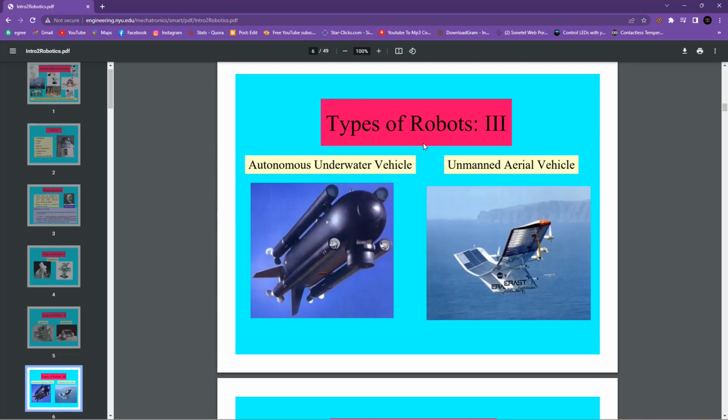In case the drone is in the air and it encounters wind, it's going to change direction or lose control. So the drone has been programmed to balance itself with some sensors. For example, the gyro sensor is able to measure the angle of tilt of the drone. If it reads any angle that is not supposed to be read, it can sense that and send a message to the microcontroller to balance the robot with the help of the actuators, which are the propellers and the motors. So that is that for drones.